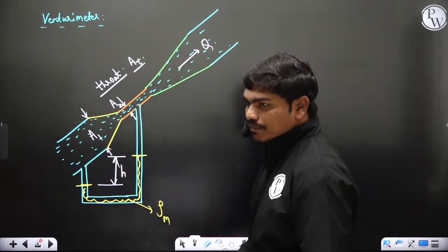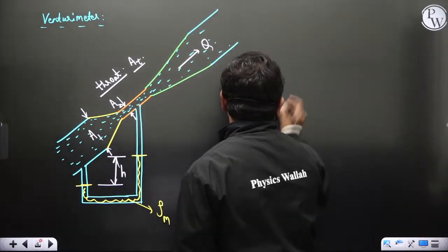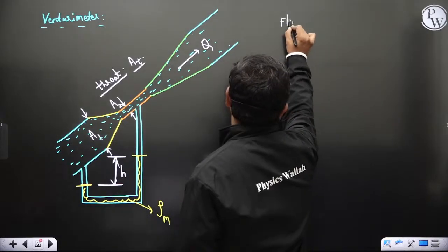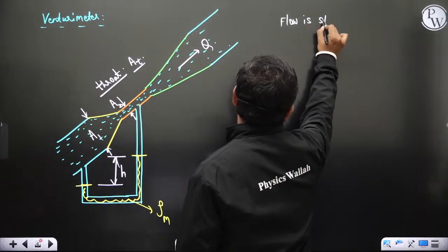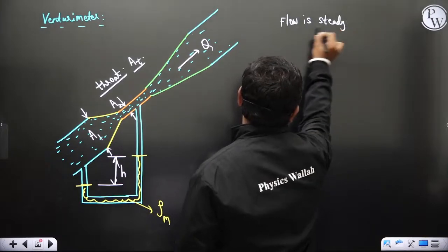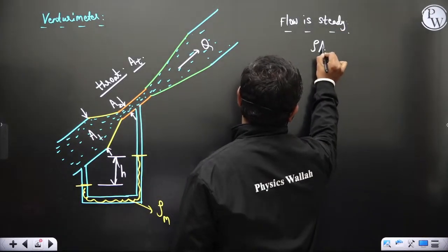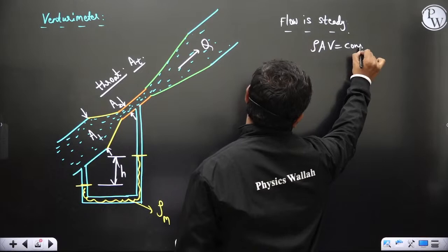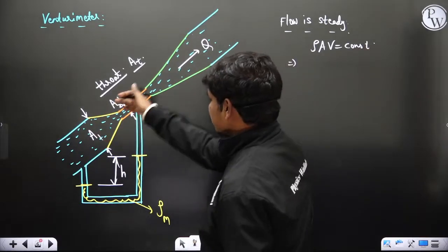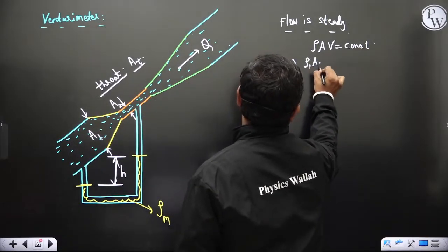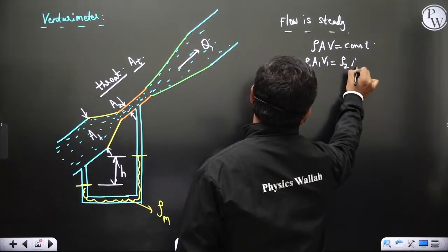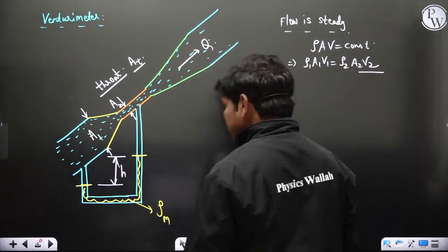Okay, so for incompressible flows, as I told you, when flow is steady, we'll see using RTT again, the continuity equation can be reduced to rho A V at any section is equal to constant. Okay, so for example, if we call this A1 and A2, rho 1 A1 V1 is equal to rho 2 A2 V2. Guys, I want to tell you one thing here.